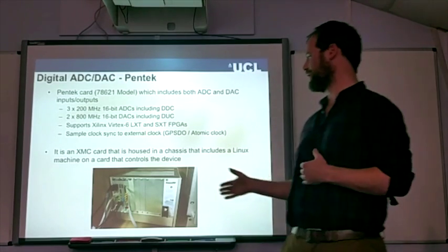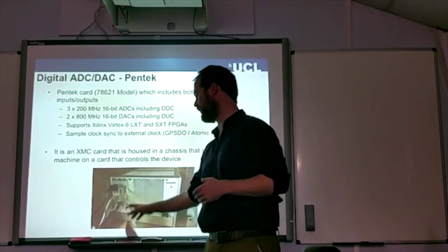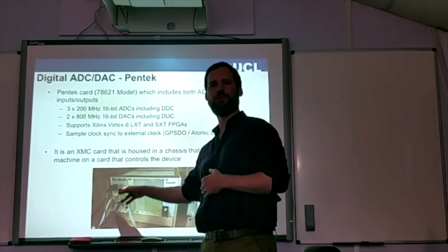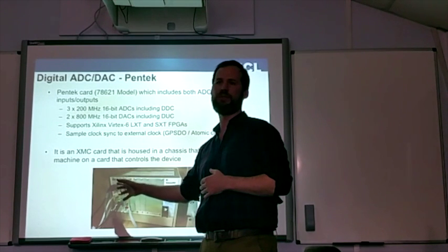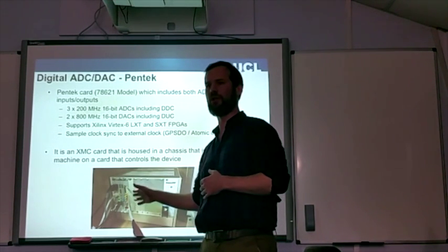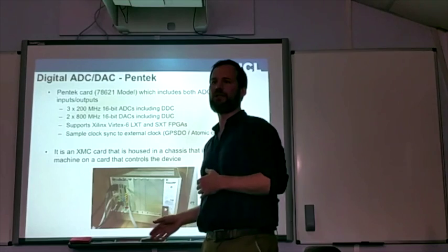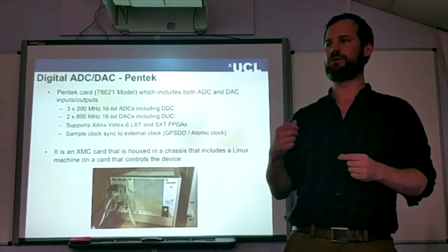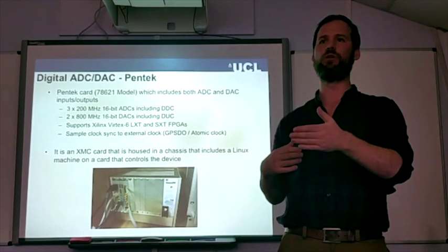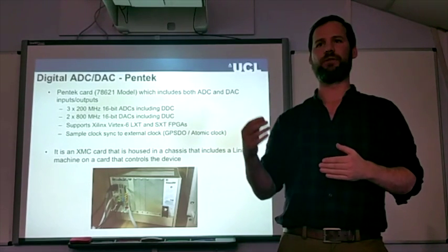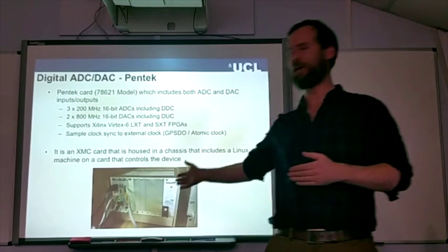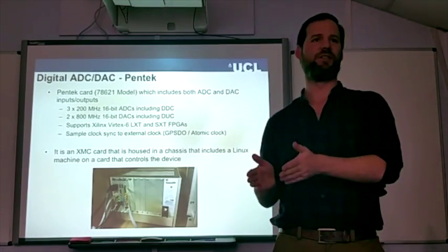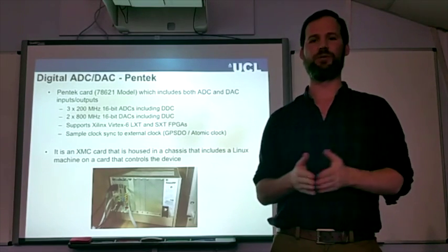This sits within a chassis that has a computer unit here, which is running Fedora Linux, and the Fedora Linux computer has all the C programming and FPGA programming that's required to run the card. And this card is then attached to the IF input of Rex. You transmit into Rex, Rex mixes up to your required frequencies, and then we were doing some loop tests within the lab, receiving our same pulse, and then digitizing back into this Pentek card and evaluating: if we send this, what comes out if it's just a loop test? Or, what do we see?